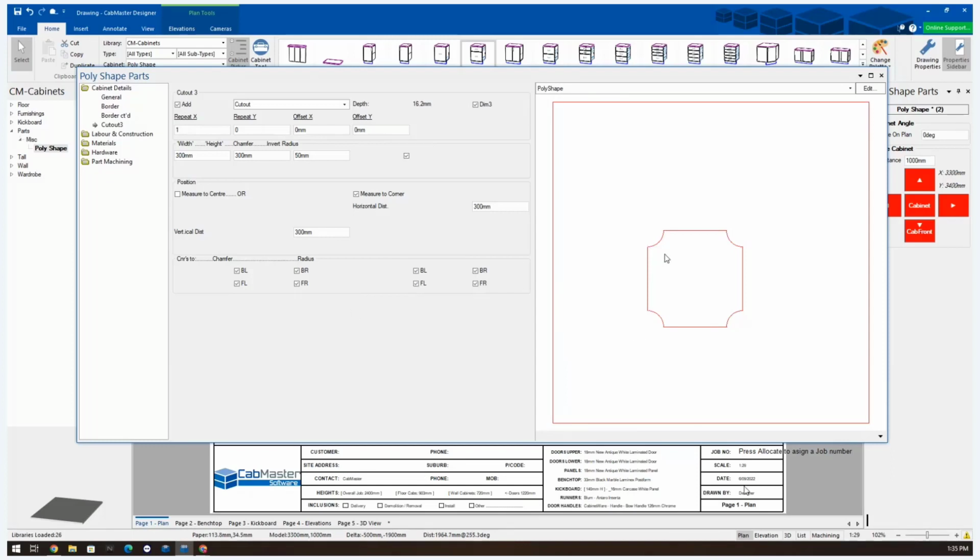So that will basically allow you to create a cutout inside it like that. It's a different way of doing the border, not the border, the cutouts, but it works just the same. And then I can repeat this 2 times, same repeating on X, repeat Y, repeat X, same offset. So if I put in here 350, it will repeat it to the middle. The only thing that changes if I go measure to center is it will move that way, but it still will stay the same distance because it's measuring from there to there rather than here to here.